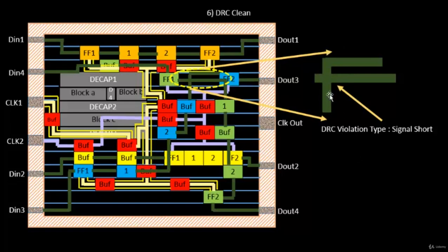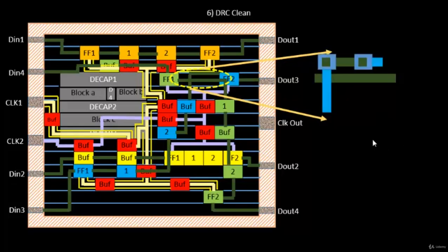What we do is take this particular layer, or any of the layers, and put it on a second layer. For example, let's say this colored wire is referred to as metal layer MN, where N is either 1, 2, or something else. We take another layer, which is MN plus 1, which is metal layer N plus 1. For example, if this was metal 2, there will be one more layer introduced on top of it. If this is metal 2, that will be called metal 3.